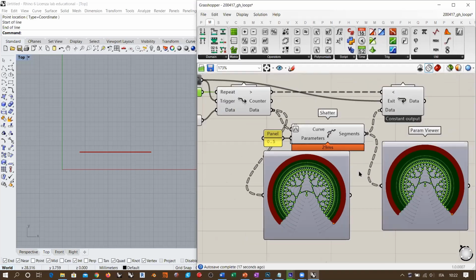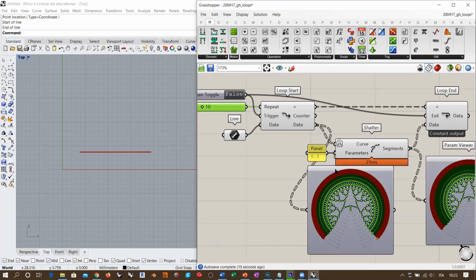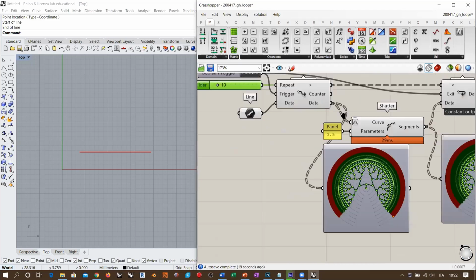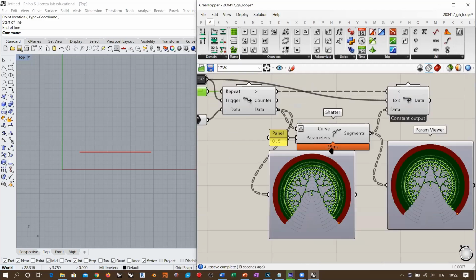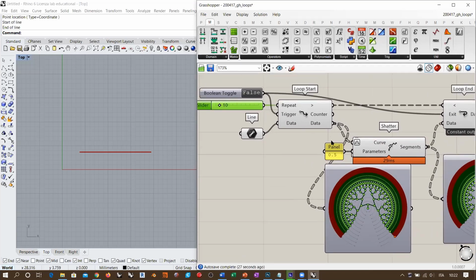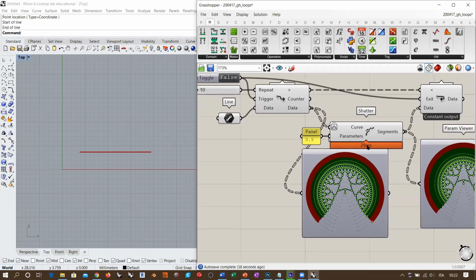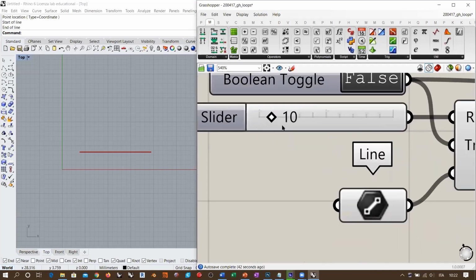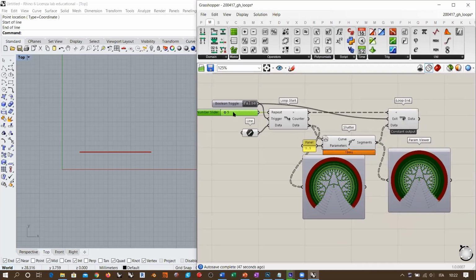Now, let's understand if we need this or we don't need this. You see how in this moment my Grasshopper has already become very, very slow, okay? I also use the profiler widget in order to understand what are the components or the functions that are giving us some problem or long calculation time. And I do recommend that you do this because this gives you an idea of what's happening in your definition. So I will decrease the amount of repetition just to have it under control.